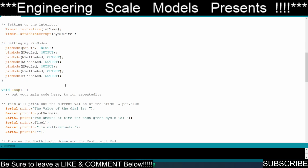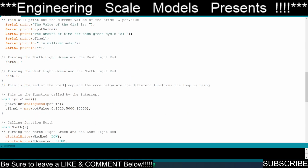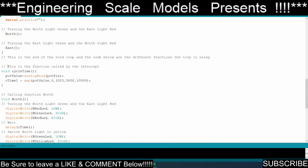That program is down after the void loop. So I have my void loop, and this is the end of my void loop. This is where my functions start, and the first function I put in is the interrupt function, called cycle time. It starts with void, has its function name, then it would have its parameters. There are none. Then an open curly bracket.